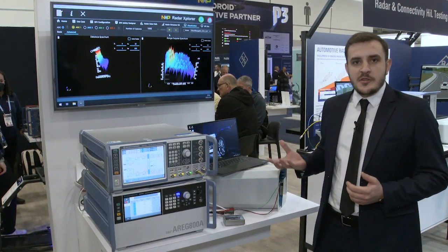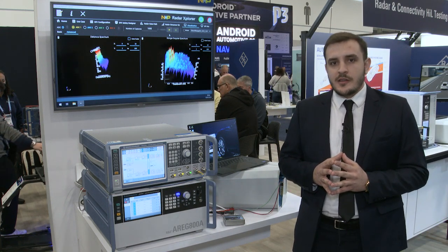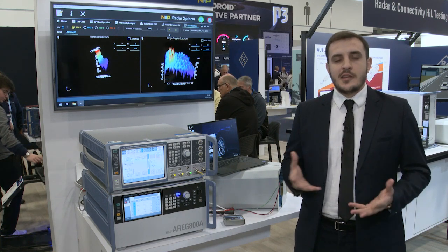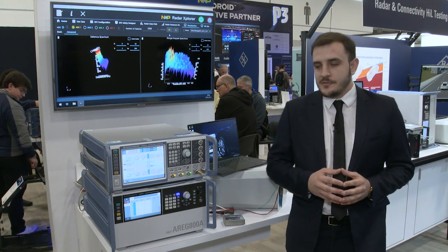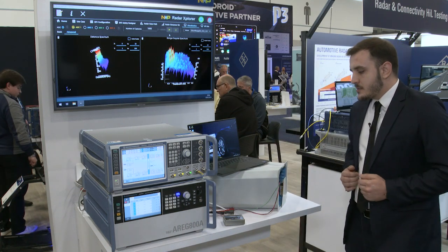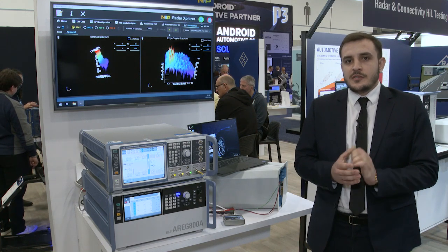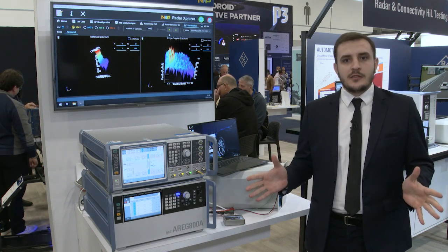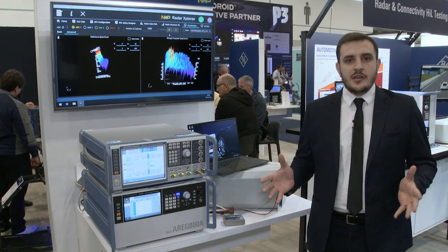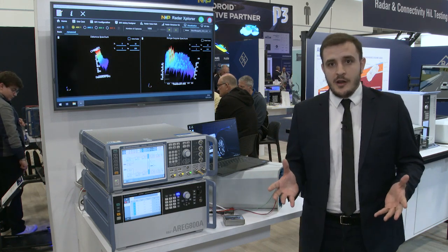From the front-end perspective, we use the REG881S, which is a monostatic millimeter wave front-end using a single antenna and being therefore suitable for testing MIMO radars. And talking about MIMO radars, I would like to mention that from the DUT perspective, here we use the Pluto radar sensor from NXP, which has the newest chipset from NXP, and it's actually the first 28 nanometer RFCMOS radar.